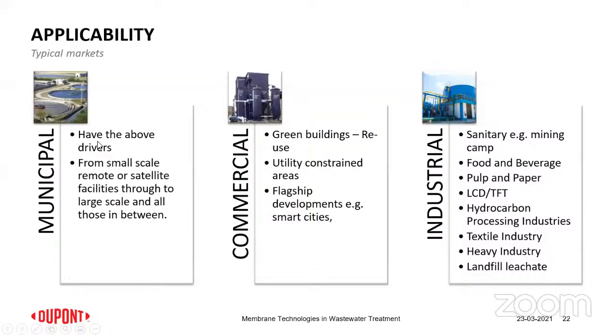In municipal, we also see a lot of large-scale municipal organizations entering into membrane-based technologies, where you have conventional processes and the same footprint and you want to increase the throughput of the same plant. You just dump in membranes in the existing aeration facility and increase the capacity of the wastewater treatment facility. So this is also seeing traction in the municipal plants.